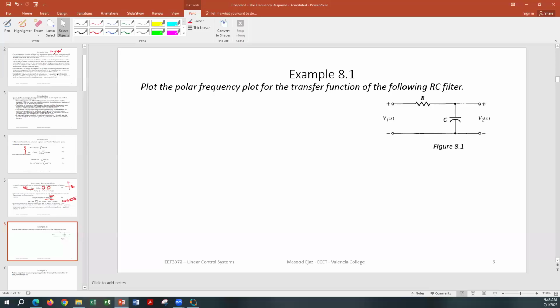distributing around the skin, or basically around the outer area of a resistor. So as you're changing the frequency, of course, we assume resistance is not changing, but as the frequency increases, all the charges, the electrons flowing through the resistor, start accumulating towards the surface area of the resistor. Thus, the effective cross-sectional area of the resistor becomes smaller, and the resistance basically increases as you increase the frequency.